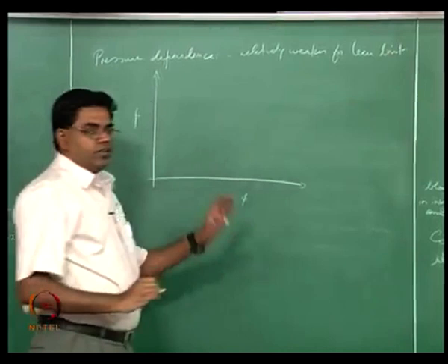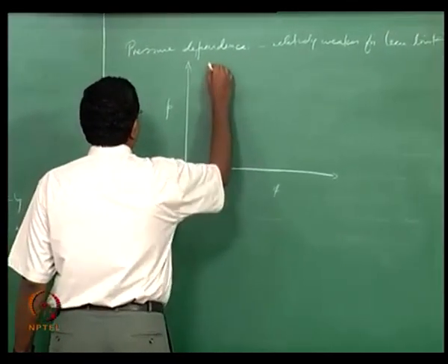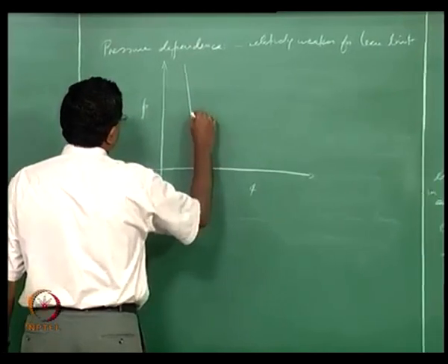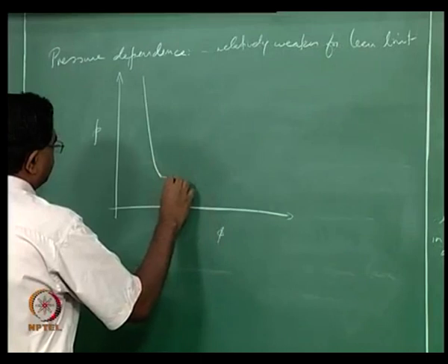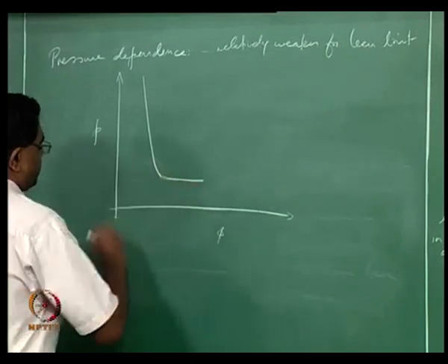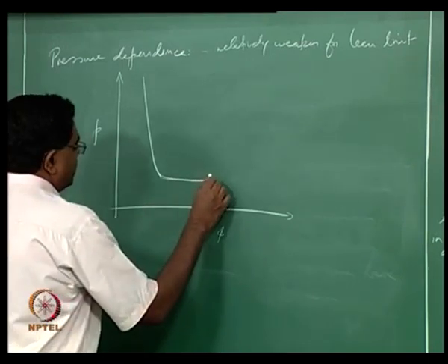Still it's sort of linear, okay. So over a range of pressures it's weakly linear, and then almost remains constant over a smaller range if you think about it, and then flattens out beyond a certain low pressure, beyond which you just have no flammability at all.